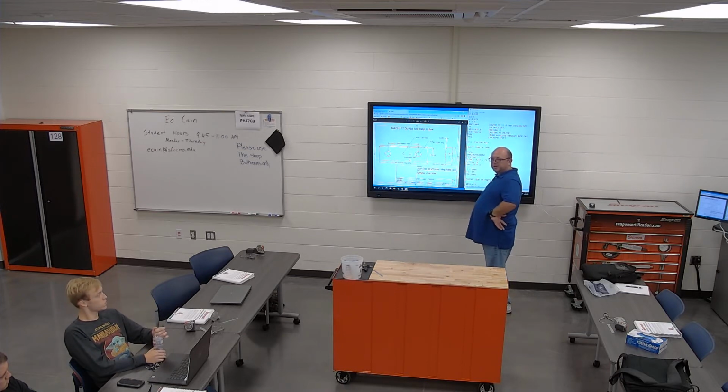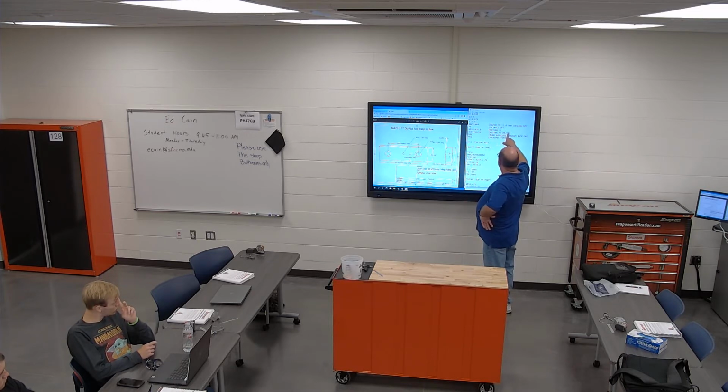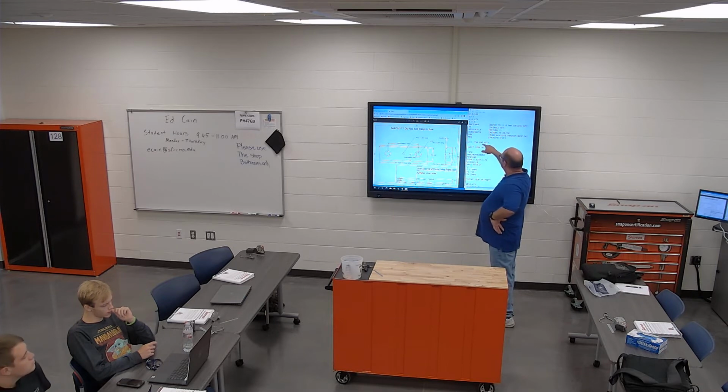You guys remember how I did that? If you just do G28, Y0, it slides the table straight to you from wherever it's at. It won't slide it over. Depending on your machine, though, you can put an X value in there for whatever you want. That's what it says here, return to X0, Y0. If you want to return to something else, you just change it to the something else. G90 turns absolute programming back on. And then M1, program stop.